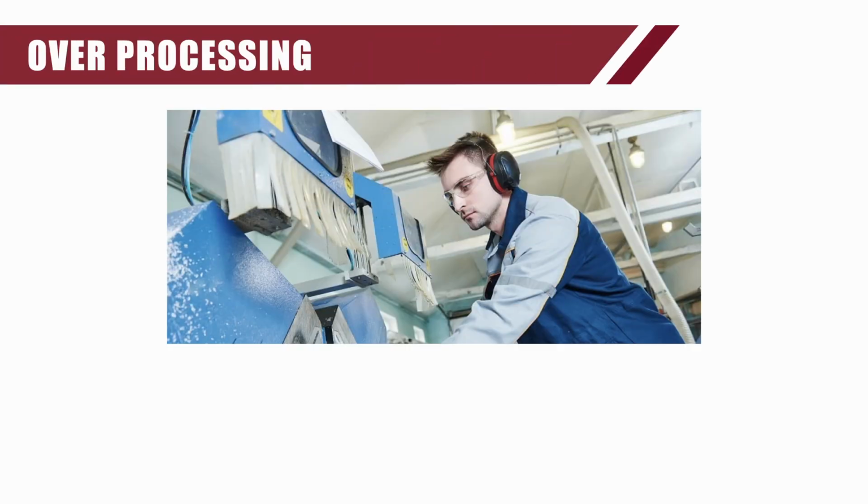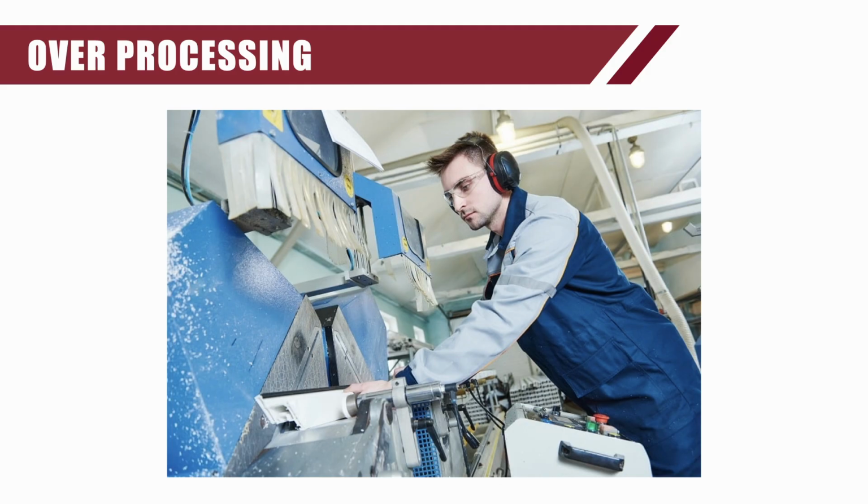Overprocessing. Ensure over-engineering of parts is not happening. If you have to explain the detail of why it's important, but the customer can't explain it, you may be overprocessing the parts. If you have 1 hour is the spec and 2 hours doesn't make it better. If the spec is 1 hour rest time, don't wait 2 hours. You're overprocessing. If the torque is set to 3, 5 isn't going to make it better.